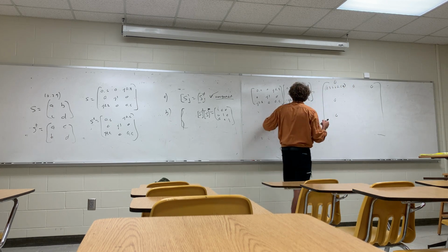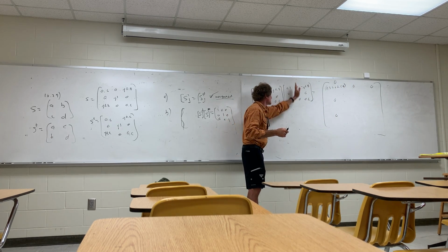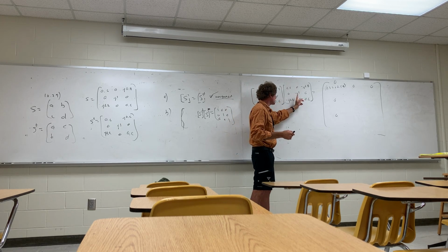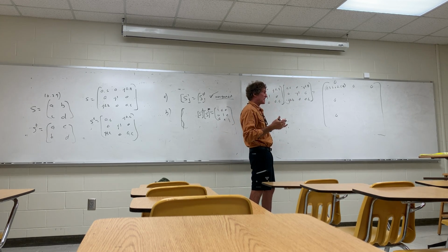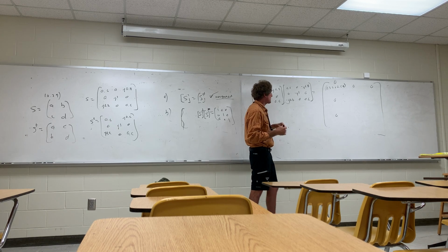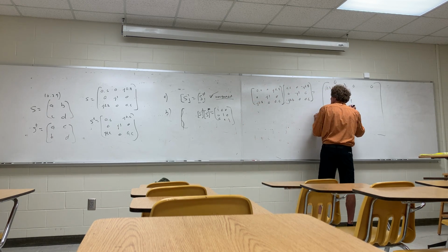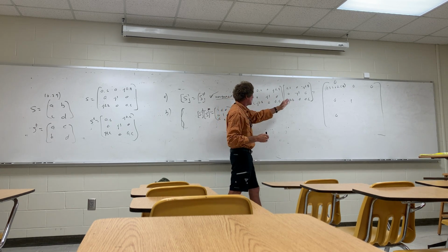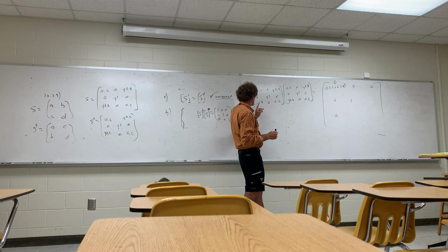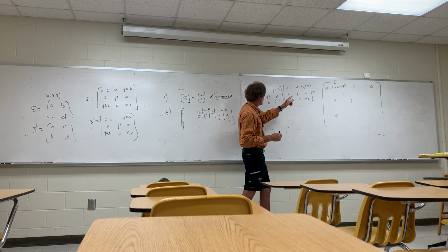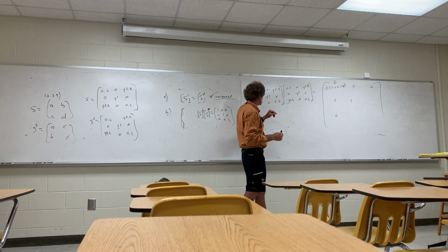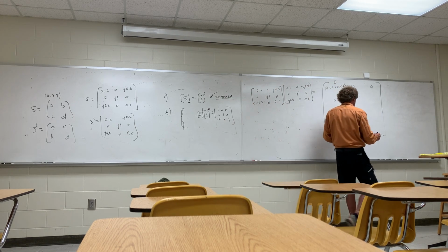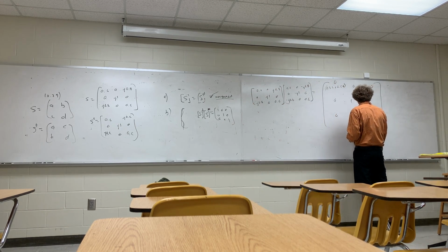That middle term is this times this, so it's going to be j1 times minus j1. j times j is minus, with a minus sign it is plus, and 1 times 1 is 1. And the final one down there in the corner, if we take this times this, we get plus j0.64, because this j times minus j ends up being 1. 0.8 times 0.8 is 0.64, and then I get 0.36, which is exactly 1 as well. So in fact, it is lossless.